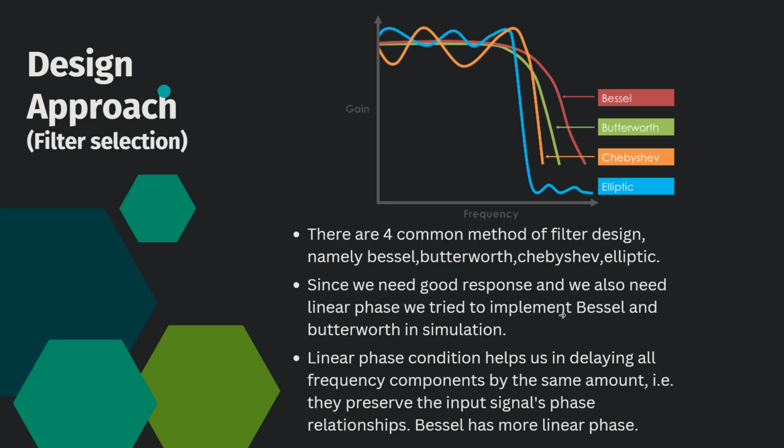And next we need to find the distortion in hardware itself. So we took the FFT plot in the DSO and changed the Y scale to the RMS voltage scale, and we noted the RMS voltage at different fundamental frequencies. Here the fundamental frequency we chose is 10 Hz. So at 10 Hz we chose the signal, and we got around 1.7% distortion.